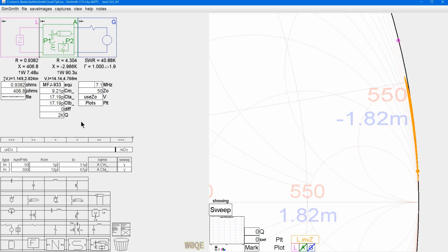Let's also look at this range, and as we make this a differential capacitor, we see the range gets smaller. If it's a ganged capacitor, it gets larger, and that's true at all frequencies. The ganged capacitor is the way this circuit really is built.